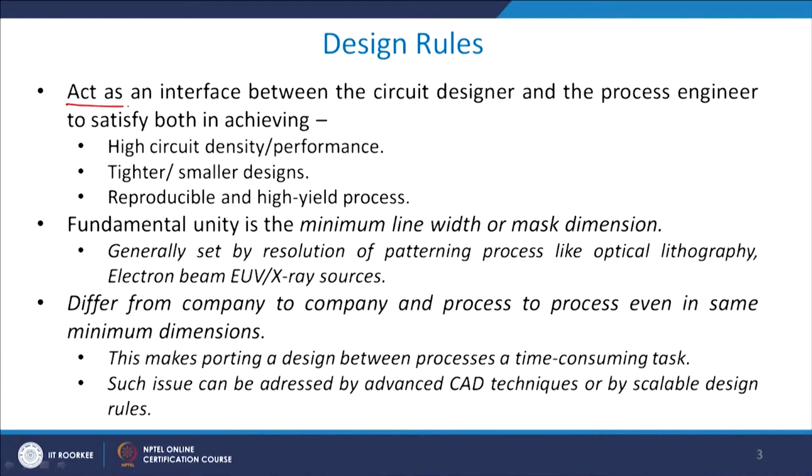So, what is a design rule? First of all, let us see that. This acts as an interface between the circuit designer and the process engineer to satisfy both in achieving high density or performances, smaller design or smaller area, and high yield processes. That is what I was saying in the first slide, that design rule checks are a common set of rules which a process engineer and a circuit designer both have to follow.